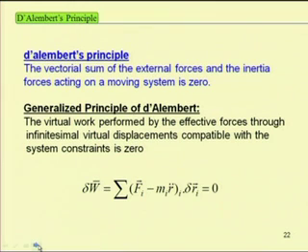So, already we are familiar with this D'Alembert principle. The vectorial sum of the external forces and inertial forces acting on a moving system is 0. By using this D'Alembert principle we are converting the dynamical system to a static system.